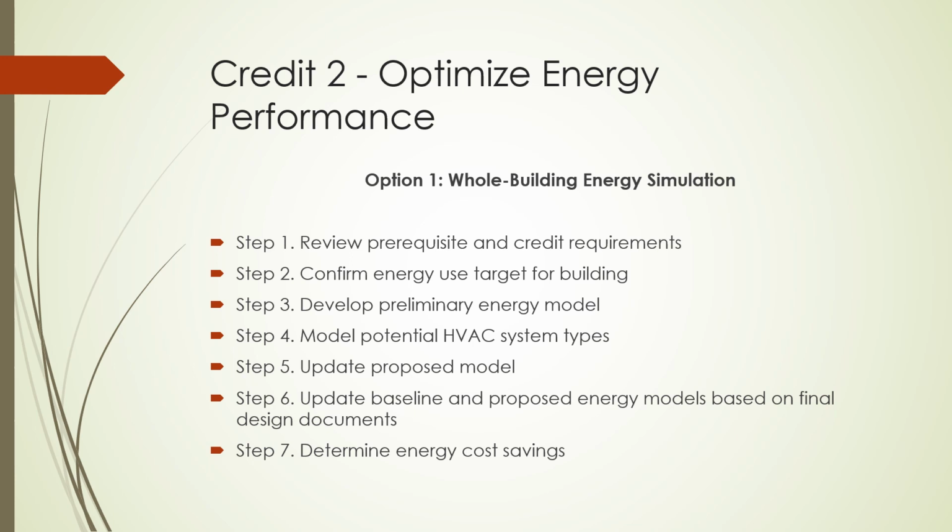Then different potential HVAC systems can be analyzed. Remember to keep updating the energy model throughout the design process so that it matches current construction details and specifications, and then update the final preliminary and baseline models at project completion. Finally, you can determine the energy cost savings of the proposed model compared to the baseline model, and this time you can include any on-site renewable energy systems as an offset to energy costs.